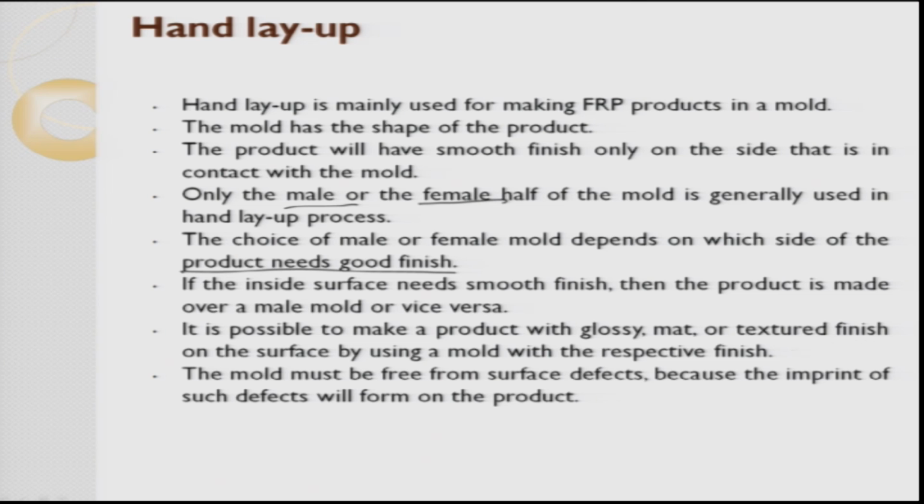a textured finish. Finally, a product is more impressive if you make it glossy. The final finish, texturing, is very much talked about today, because texturing gives an improved feel while using the component. Texturing can be done in many ways on the surface by using a mold with the respective finish. The mold must be free from surface defects. This is very, very important.